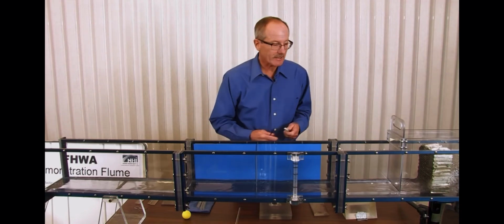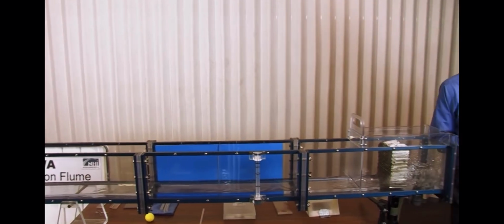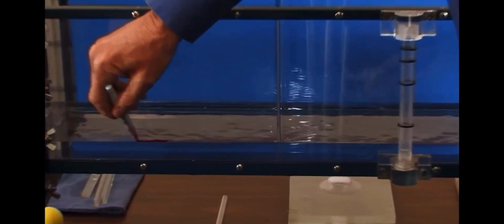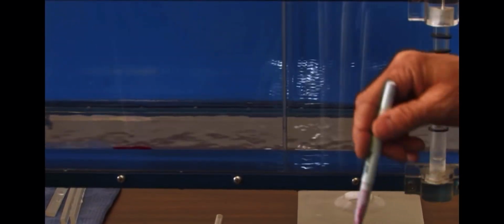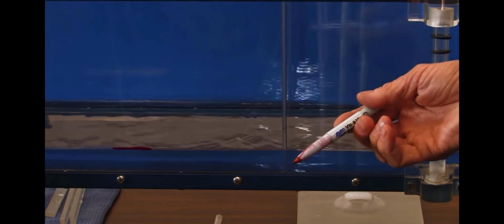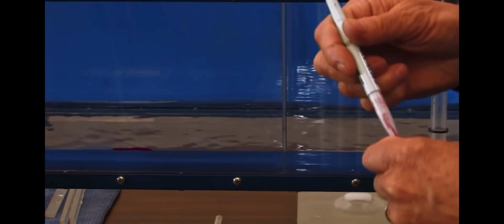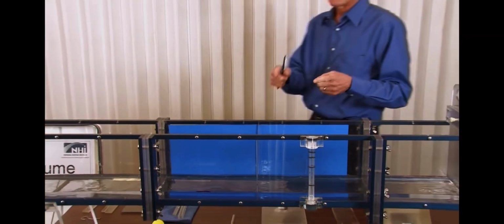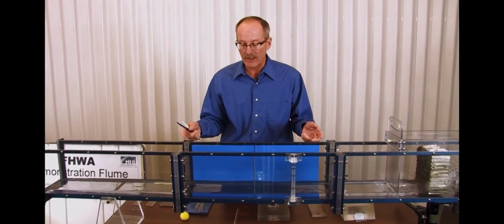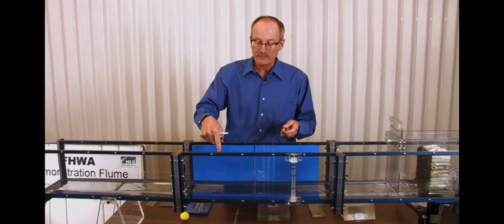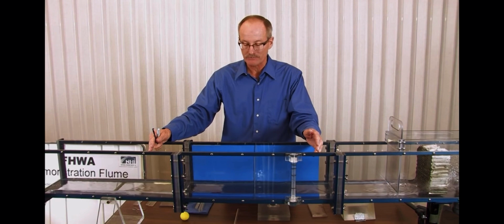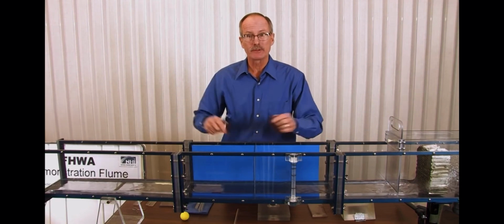And what depth would I get? I should get exactly the depth that we see on the flume if I'm in steady uniform flow. Manning's equation, given good input for the discharge, the slope, and the n value, should predict exactly what my flume is now doing in steady uniform flow conditions. We call that depth the normal depth.